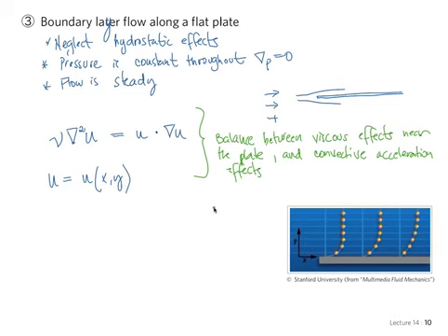There are approximations and so on, and some ways of analyzing this, but already we can't write down a closed form solution. We can see that the effect of the flat plate is being felt on a wider and wider region as you go along. Basically, the idea is that the boundary layer thickens in the direction of flow. That's the concept of boundary layer. We will come back to boundary layer later on.